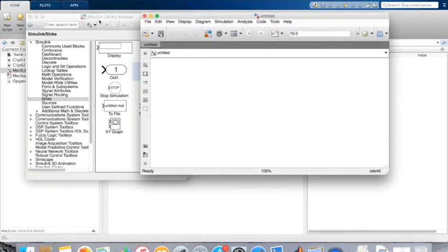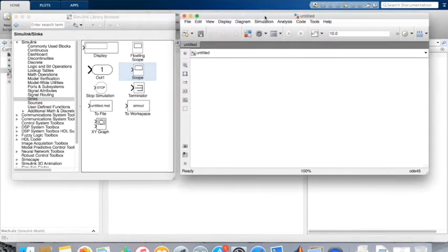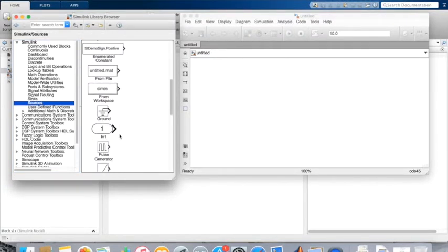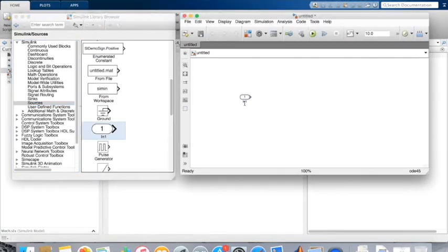Once we've done that, we can create a new Simulink model by pressing this button. Then we get an empty field in which we can build up the model. First, we will start with the input profile of the road, and therefore we look under the sources, and there we will find the generic input. And then it's perfectly logical to give this input the name u, which is the position of the road profile.